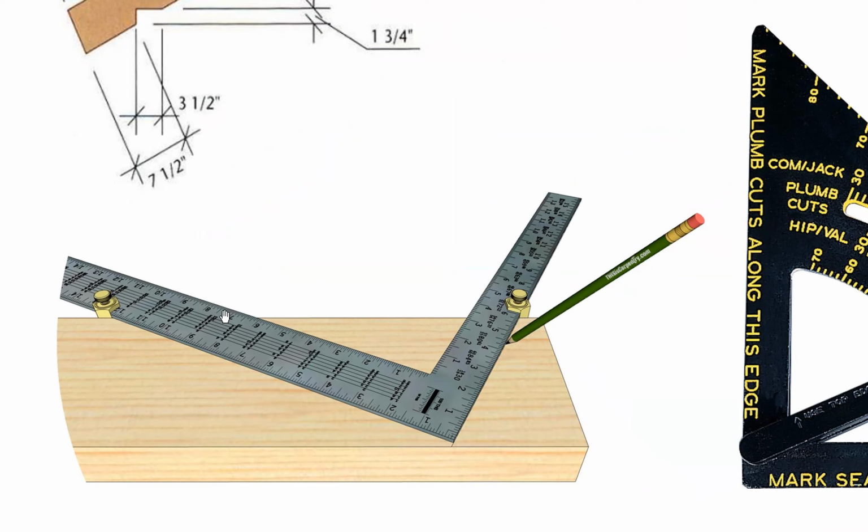So we're working with the top edge now. They would line up 6 inches on the framing square and 12 inches on the other side. So this would represent the rise, and this represents the run, which remains constant. They would line up the two numbers. Here they have something that they literally lock in place so it can't shift.